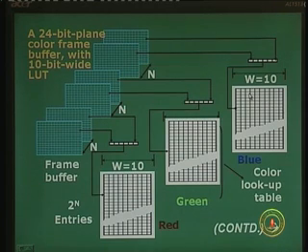That means we are looking at intensities of 2 to the power 10, which is about 1024, 1k. Out of 1024 possible intensities of red separately, green separately, and blue separately. That means the entire range from the darkest value of a color up to the brightest value of that color is now split into 1024 different quantum levels or discrete steps, from 0, 1, 2 up to 1024 minus 1, or 1023. Where is this 1024 coming from? Well, W equal to 10, 2 to the power 10. So that is the way it comes out.